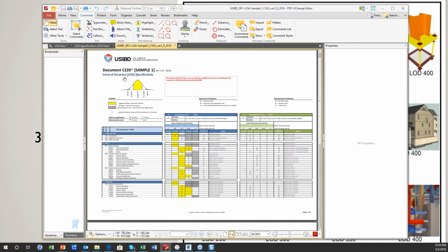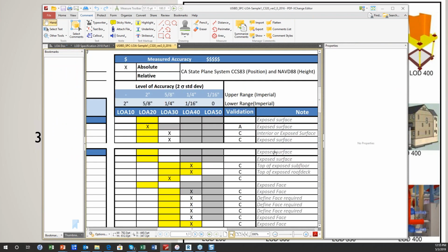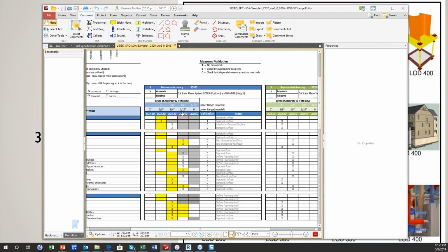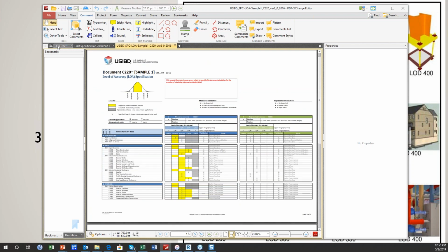This is also one, level of accuracy, and how accurate your scan is going to be. Most laser scans we can get within this 5/8 to 1/4 inch range. That's where your level of accuracy typically is going to be with the scan, in this 1/4 inch area, unless you're going out to 300 or 400 yards. So you want to know what level of accuracy they're going to scan it at. So ask that question.